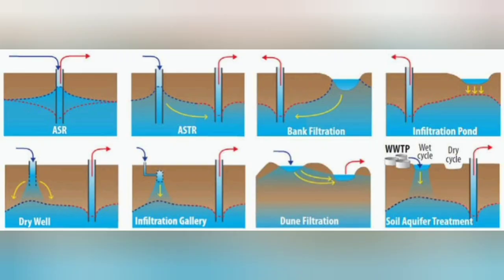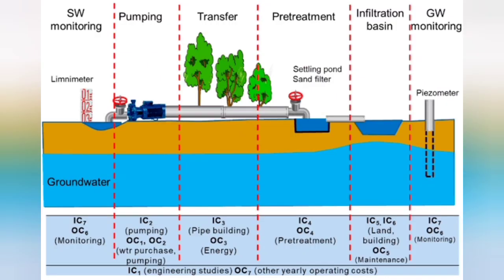Periodical removing of the mud cake or discing or scraping of the surface layer, installation of a filter on the surface, the permeability of which is lower than that of the natural strata, addition of organic matter or chemicals to the uppermost layer, cultivation of certain plant covers, notably certain kinds of grass,